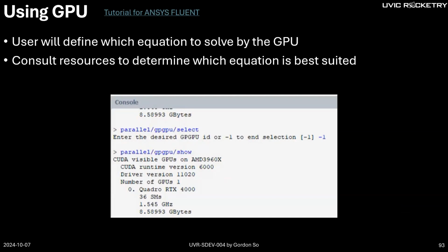However, be careful because when you use graphics cards, that could be a bottleneck. If your graphics card is something like a GTX 70, like the old ones, it will probably be a bottleneck. So make sure you know your hardware well. But this is how we set up to use a graphics card in ANSYS. It actually allows you to run really fast, which is really good.